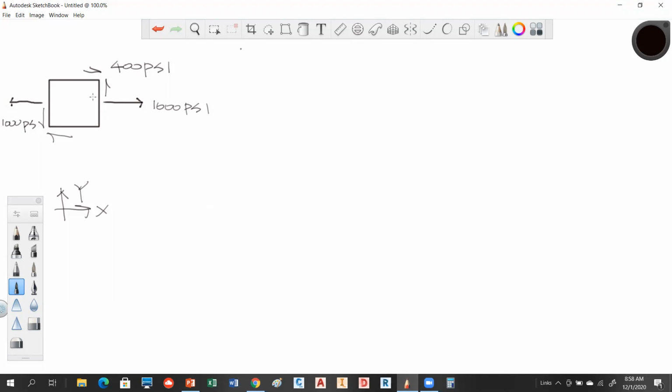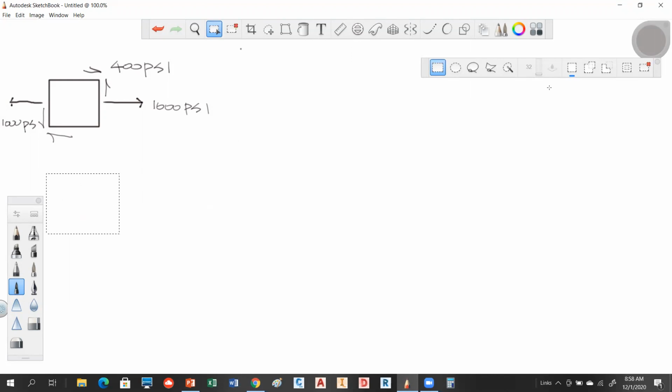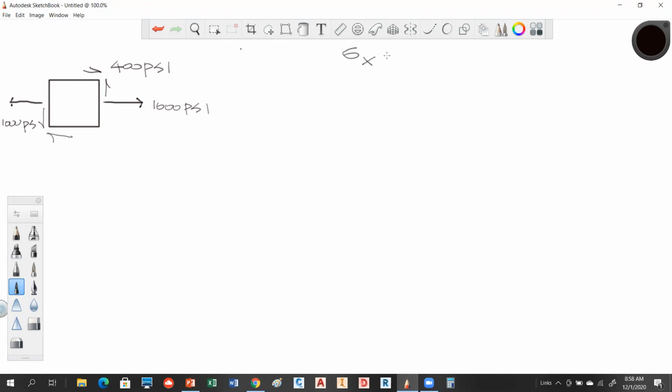So the first thing you do when you develop Mohr's circle, here's what I do. If you get your coordinates first, then it all just comes together. So let me put those over here. The first thing is I can determine sigma x. This is the X normal stress, and since it's tension, we're going to say tension is positive. So we're going to call that 1,000.